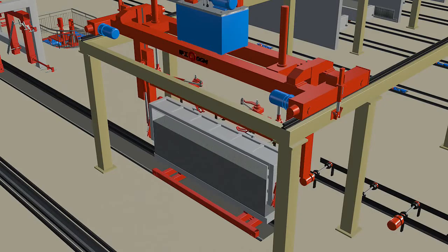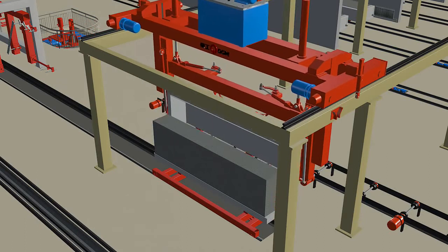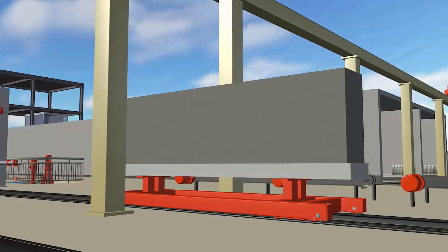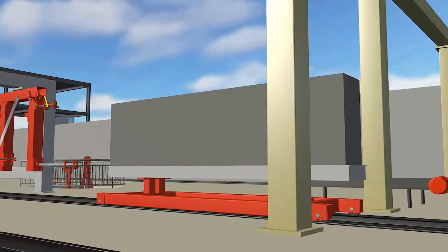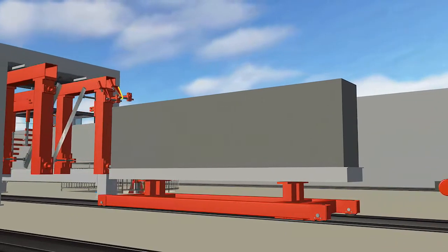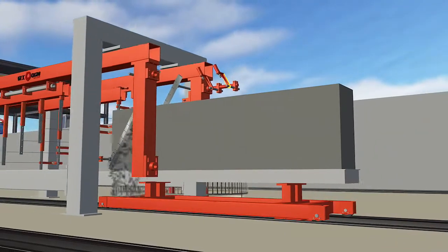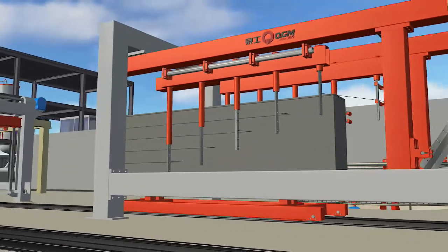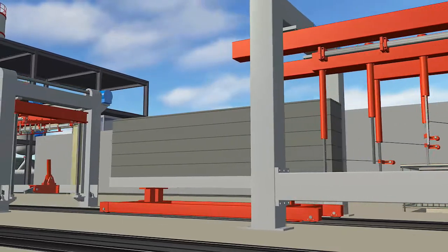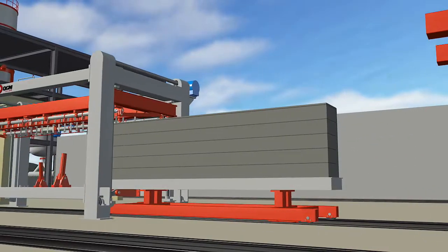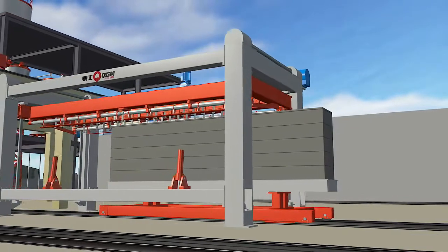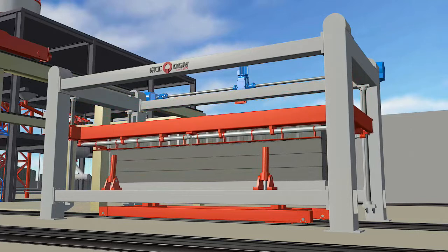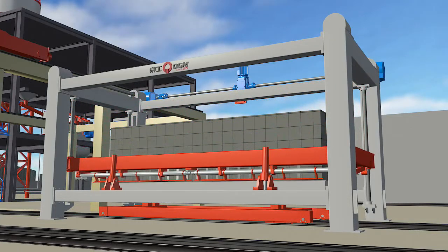Then the manipulator separates the cake from the mold. After demolding, the cakes are cut in the cutting machine. The cutting car with the cake goes through the vertical device for vertical cutting. During this period, the thickness is cut by the cutting blade and horizontal cutting machine. Then the transverse frame lands top down vertically and the wires swing for the cutting.